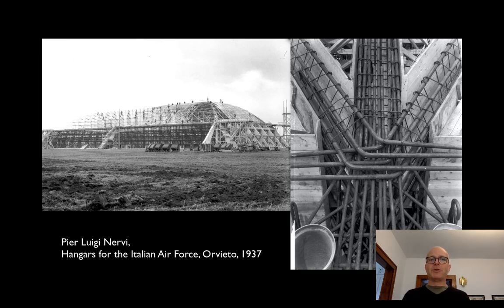And all of the timber that went into that very complex formwork ended up being discarded. You can see, too, on the right that this is only a concrete structure in appearance. Because of the dead weight of all of that concrete in the vaulted roof, even with the lamella system, you can see what one of the connections looks like as all of these lamella ribs come down to those buttresses, right? That's essentially a steel structure with concrete kind of around the outside. All of that reinforcing is necessary to take the shear loads between the roof and those buttresses.